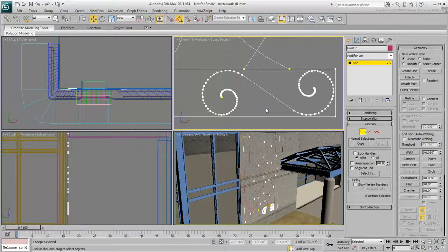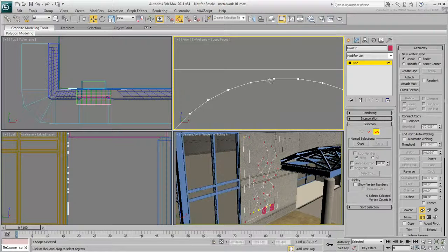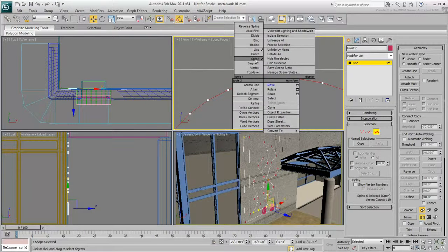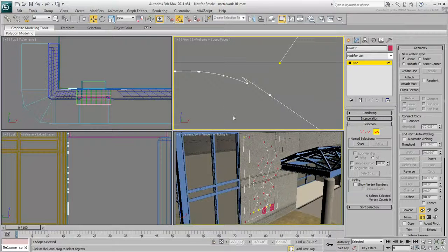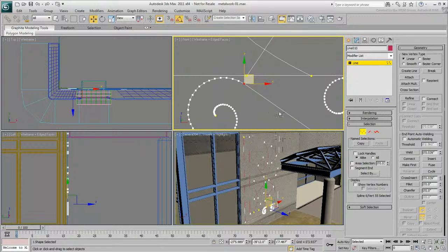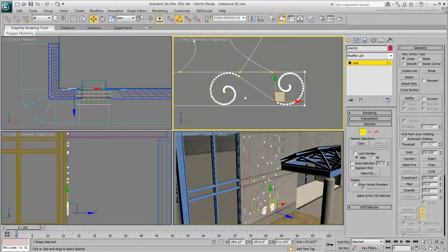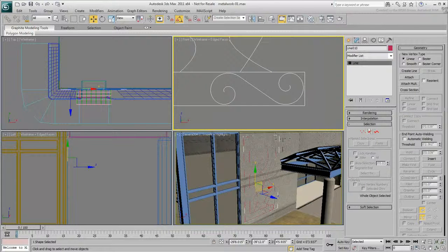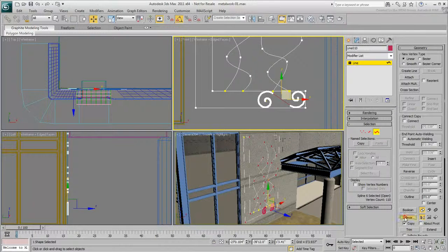One last note. Helixes are made of linear segments, and that should be fine when seen from a distance. If you need to turn helixes into curves, then you can do so at the spline level. Select the spline combo, right-click and choose Curve from the quad menu. Double-check to see if some Bezier handles are not out of shape, and adjust where necessary. You can change individual vertex types, not all of them have to be Bezier. From this point on, you can make the necessary mirror copies to duplicate the spirals. This can be done using Mirror Copy or by using Shift Rotate and Shift Move.